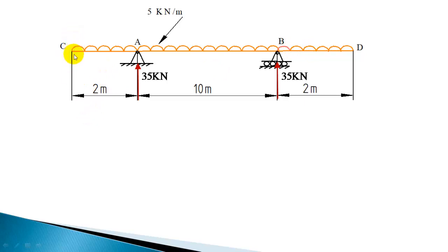Now right of C, if you take, this part of UDL is infinitesimally small, so there is no load immediately left side of the section plane. So you are taking the section plane right of C, but looking for the forces on the left side of that section plane. So there is no force there, and shear force will be 0 at right of C. This part of UDL is infinitesimally small, so shear force right of C is 0.